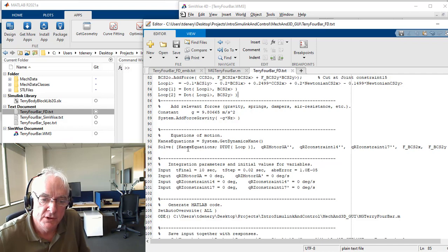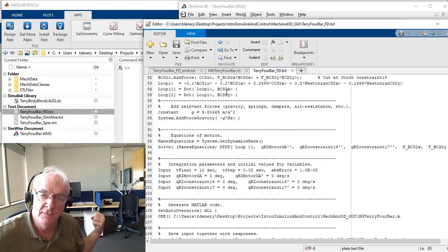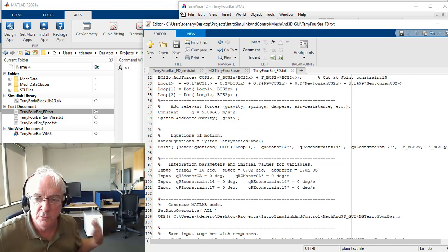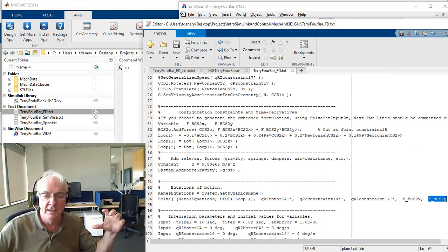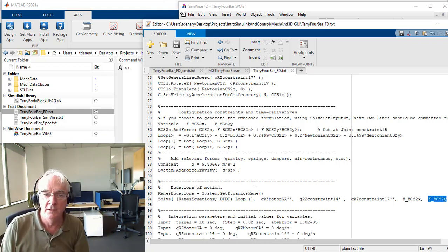You take the general equations of motion, the kinematics of each revolute joint being accounted for, and add the two additional algebraic equations you get from dotting with x and y. With those 5 equations, you can impose that loop constraint, and you solve for 2 additional variables. These are good ones to have, because they're essentially the force required of the bearing to hold the mechanism together at that one joint, which we represented with a spherical joint on a slot.